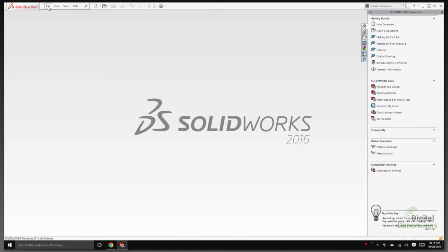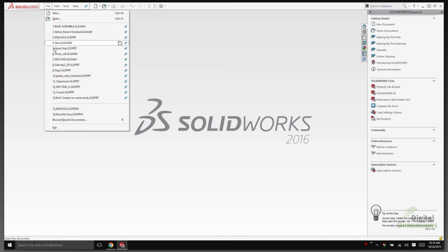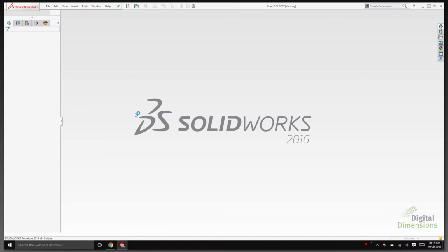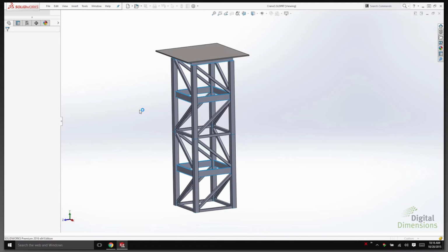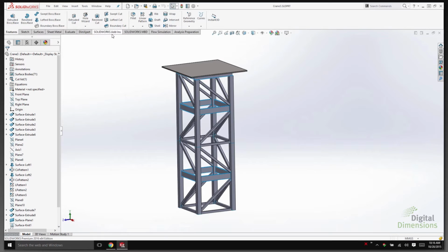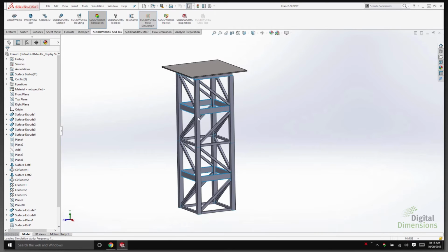Now, what the under constrained bodies was showing us is all those different pieces that, with that weld gap, the directions they were moving in, all the degrees of freedom that they were not defined in. So a new option for SOLIDWORKS 2016 for these shell faces, all these different shell components that we've created, is a new option in the global contact set for the non-touching faces for shell edge to solid shell face pairs.